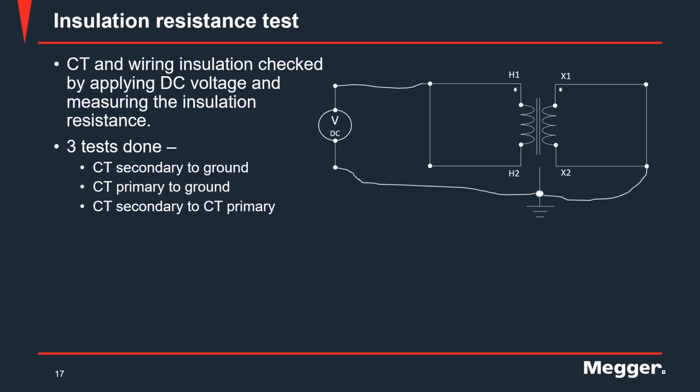When we are doing the excitation curve, the idea is to generate the amount of flux necessary to have the induction on the CT. And at a certain point, saturation is going to be reached as we increase the voltage.